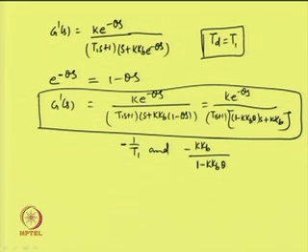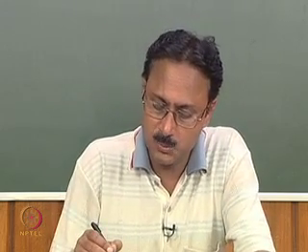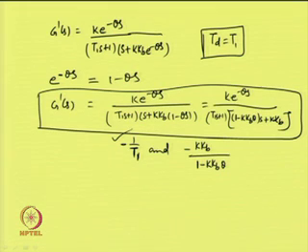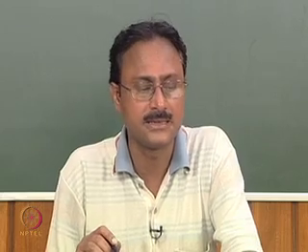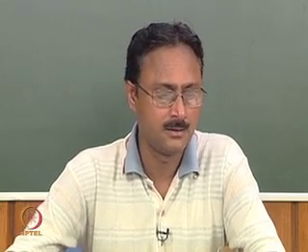Now, T 1 is the process parameter, we have no hold over that, and T 1 is assumed to be positive, but we do not know the value of T 1, but anyhow the pole is located in the left half of the S plane. Now, with suitable design of k b, it is possible to locate the other pole of the modified process at suitable locations, that is at far left in the S plane.